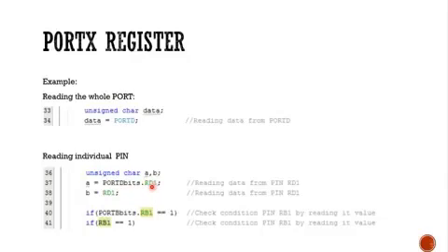So this means that the value from bit number 1 port D need to be copied and then pasted into variable A. So right now port D bit 1 is an input. Okay, so we need only read data. So you can also write in the form of RD1, the value of bit RD0 put into variable B.